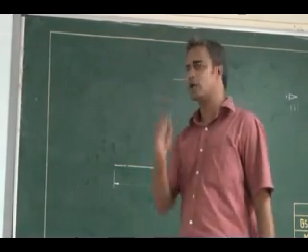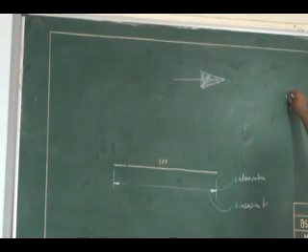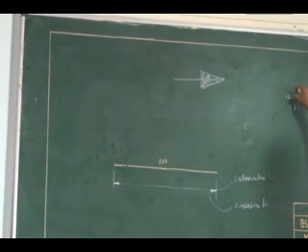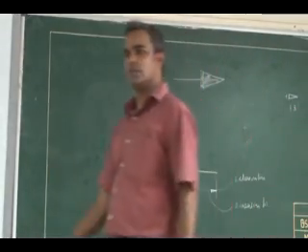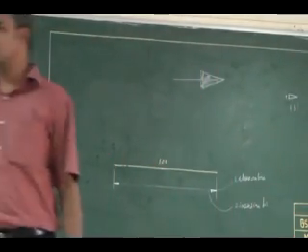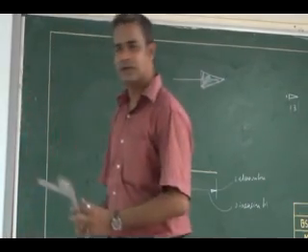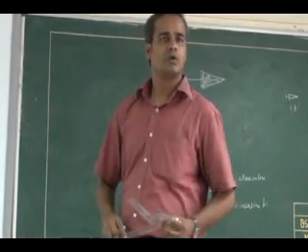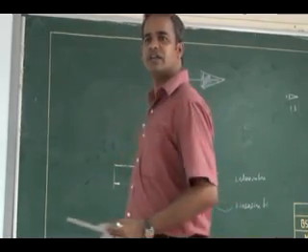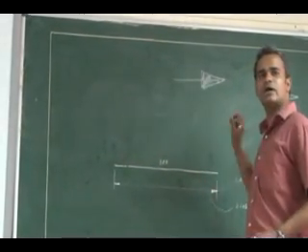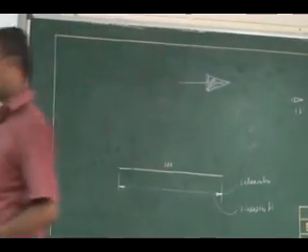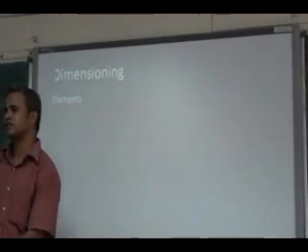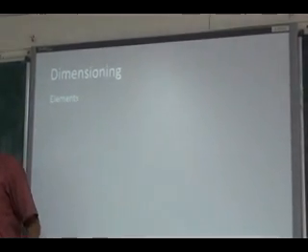Normally you can have 1 mm or 1.5 mm approximately. We cannot measure it exactly, because when drawing you can have 1 mm or 2 mm height, and the length of the arrowhead can be about 5 mm. Approximately you can have the ratio. Is it clear? Dimensioning is for all of you, so you should not make mistakes in this. In the extension line you should maintain a gap. These are the elements involved in dimensioning: extension line, dimension line, and the arrowheads.